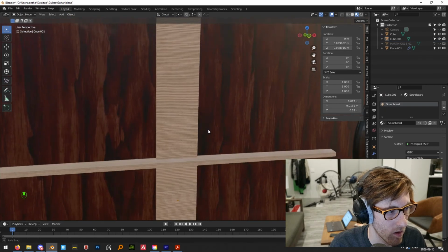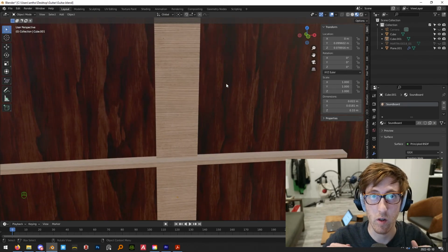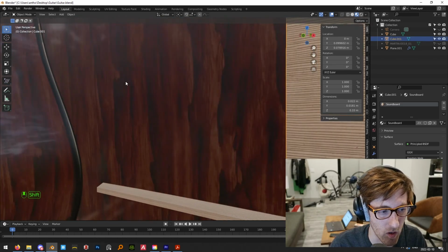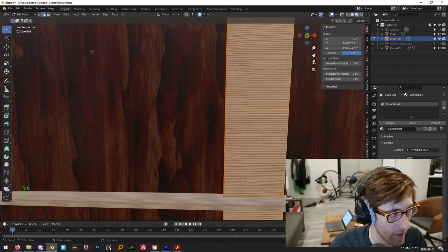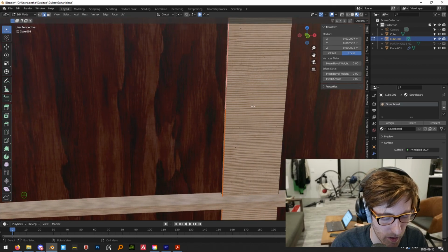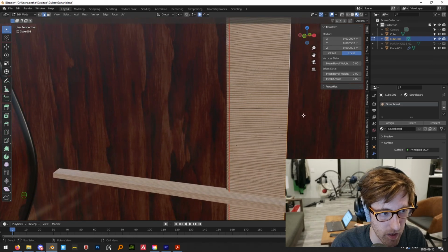And there we go. Now one other thing about this is that this should also be maybe a little bit rounded at the top. This is maybe going a little overkill with details here, but I'm just going to hit tab, select this top edge and GG to drag it inwards a bit. And the same thing with this one on the right.